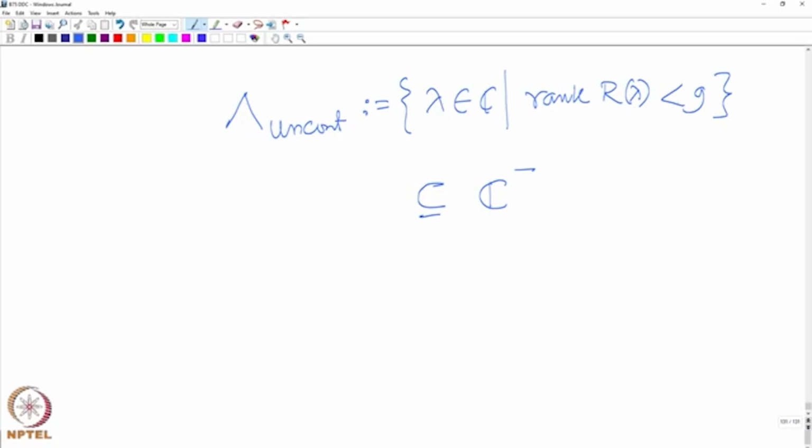When you put this controller, these modes you will not be able to change. So, each of these gives you trajectories like e to the power lambda t, which go to 0 as t tends to infinity. So, no wonder in such a scenario the system is called stabilizable.